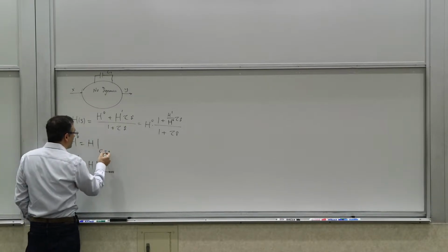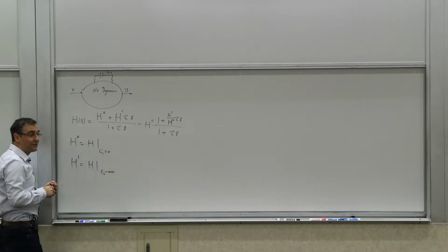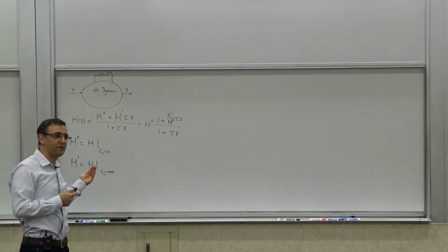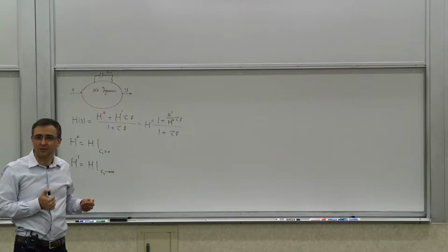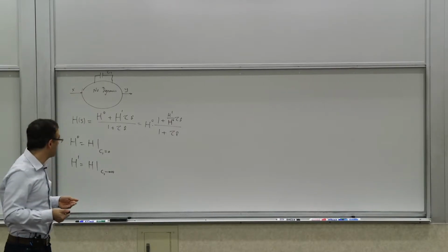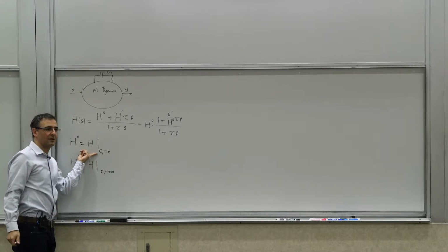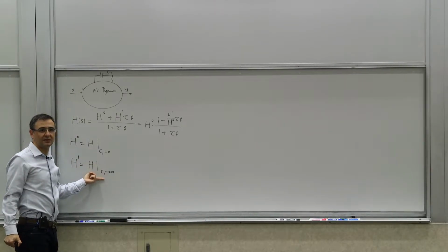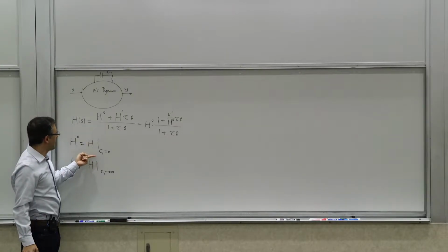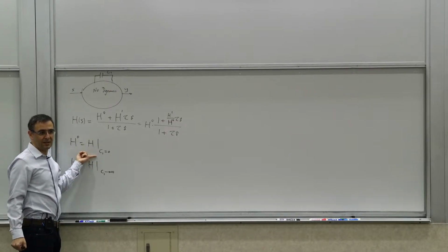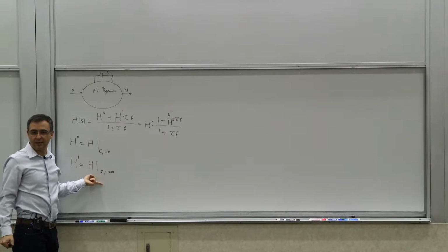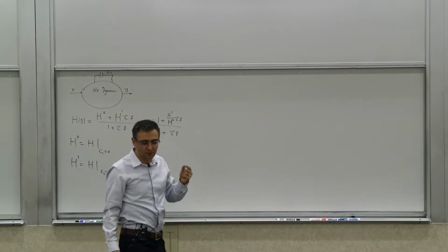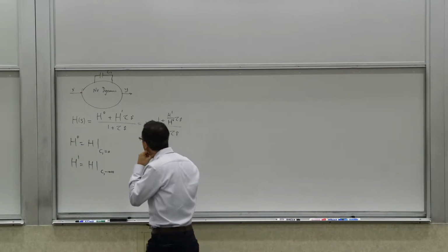Now being infinite valued or 0 valued means different things for capacitors or inductors. For a capacitor, being 0 valued means what? It's an open circuit. And being infinite valued means short circuit. For an inductor, it would be the opposite. Being 0 valued is being shorted, and being infinite valued is an open. So you should keep this in mind. In general, we are either setting it to 0 or infinity. So that's what these mean.